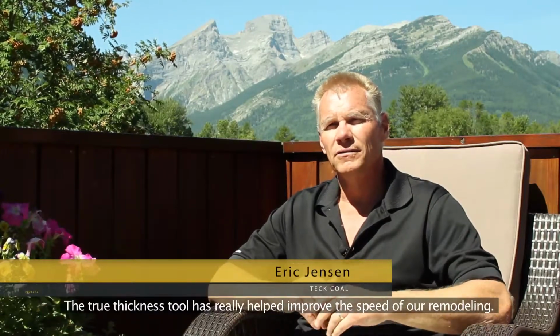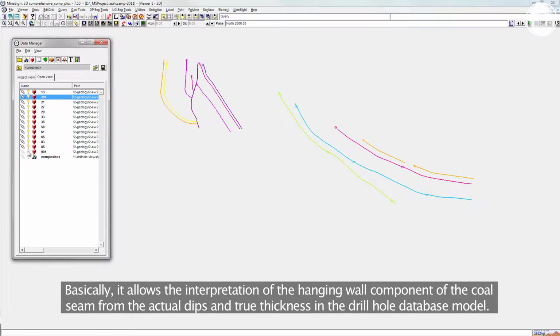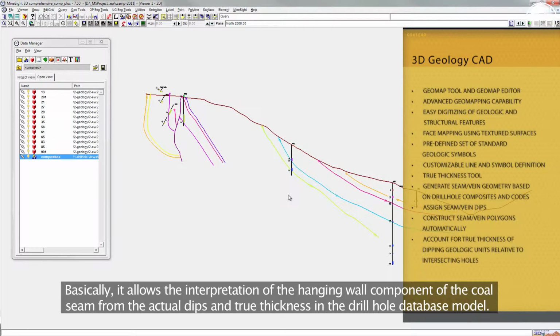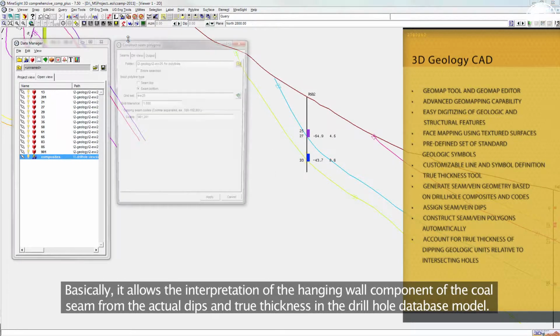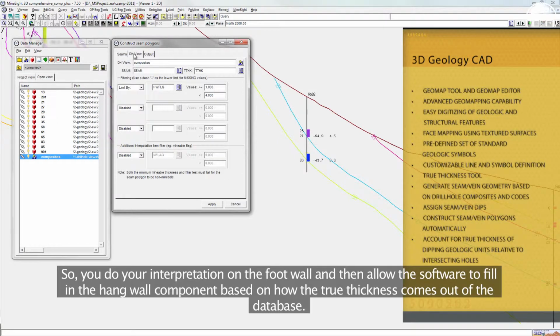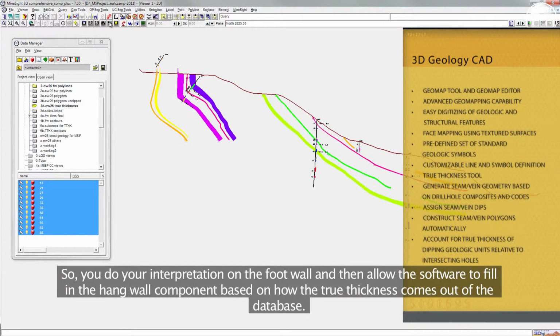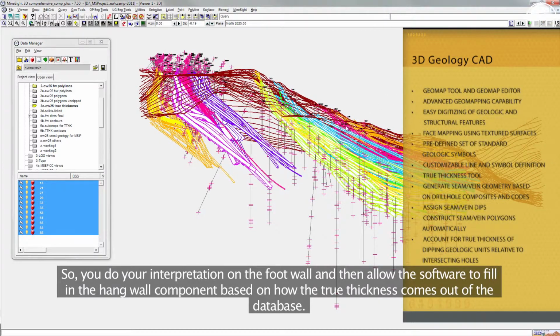The True Thickness tool has really helped improve the speed of our remodeling. Basically, it allows the interpretation of the hanging wall component of the coal seam from the actual dips and true thickness in the drill hole database model. So you do your interpretation on the footwall and then allow the software to fill in the hanging wall component based on how the true thickness comes out of the database.